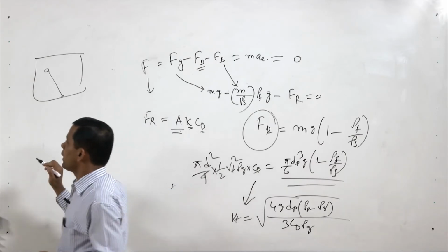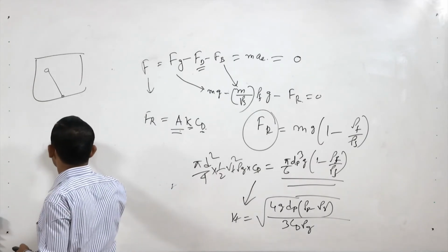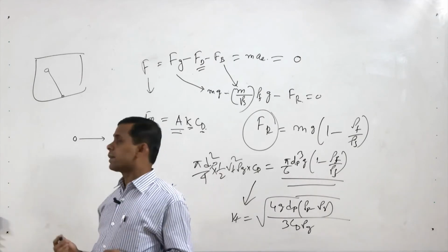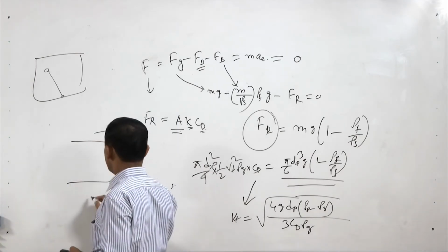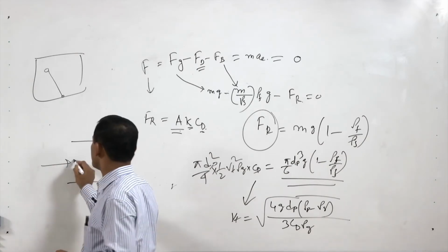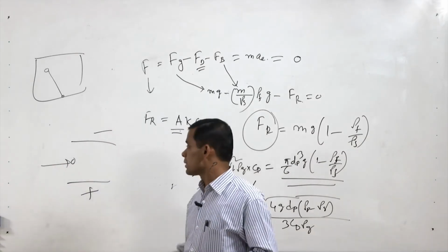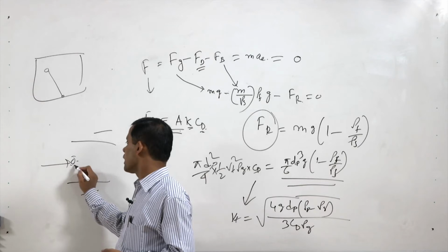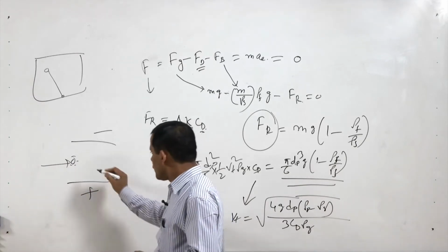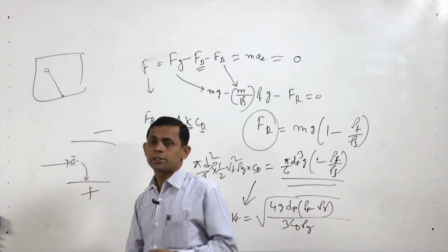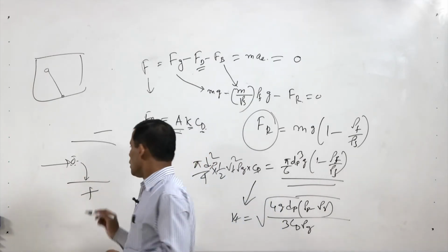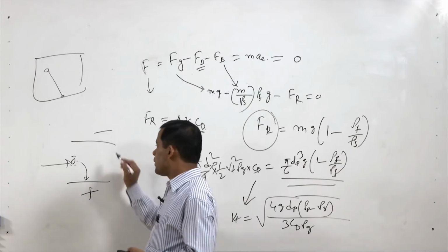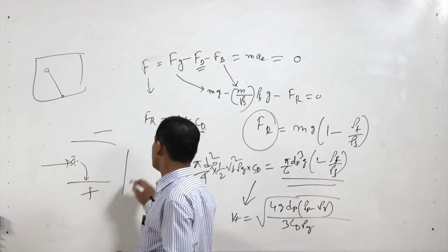But when we use an electrostatic precipitator, the particle is attracted by some force. One surface is negative, another is positive. We send the particles through this. The particle has a negative charge around it, so it is attracted by the surface, and once it reaches the surface, it settles. These plates may not be horizontal; they may also be vertical plates.